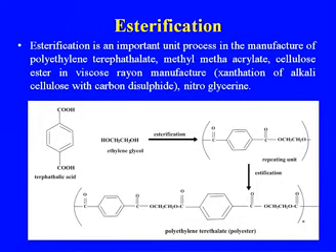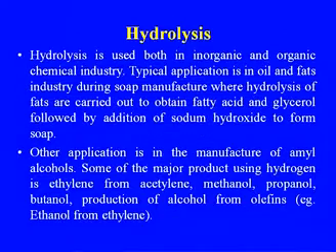Esterification is an important process in the manufacture of polyethylene terephthalate, methyl methacrylate, cellulose ester in viscose yarn manufacture, and nitroglycerin. Hydrolysis is used both in the inorganic and organic chemical industry. A typical application is in the oil and fat industry during soap manufacture. Hydrolysis of fats is carried out to obtain the fatty acid and glycerol, followed by addition of sodium hydroxide to form soap. This is the process we are using in the case of soap manufacture.